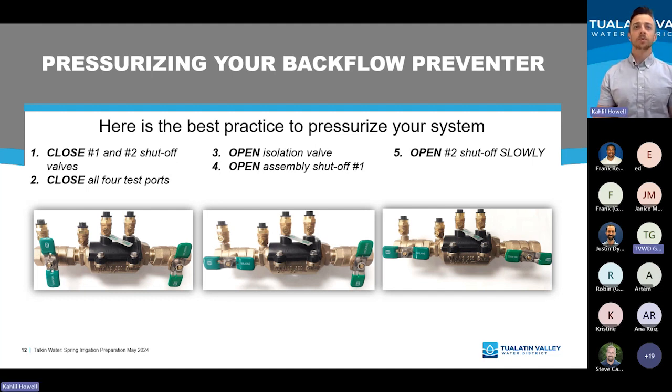Once you're at this point, we are ready to open shutoff valve number 2 to introduce pressure up to your solenoid valves. Do this step slowly so you don't cause any water hammer to your solenoid valves. And at this point, you have pressure up to your sprinkler system, and Steve will cover working your timer later on for the timing of your different zones.